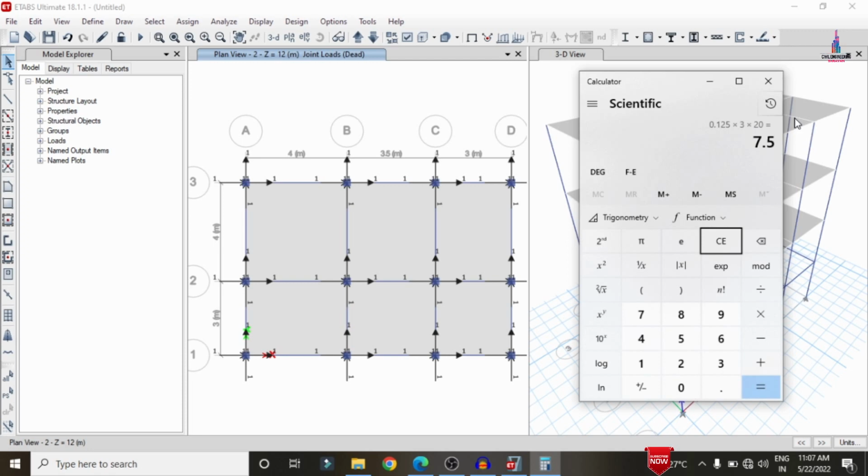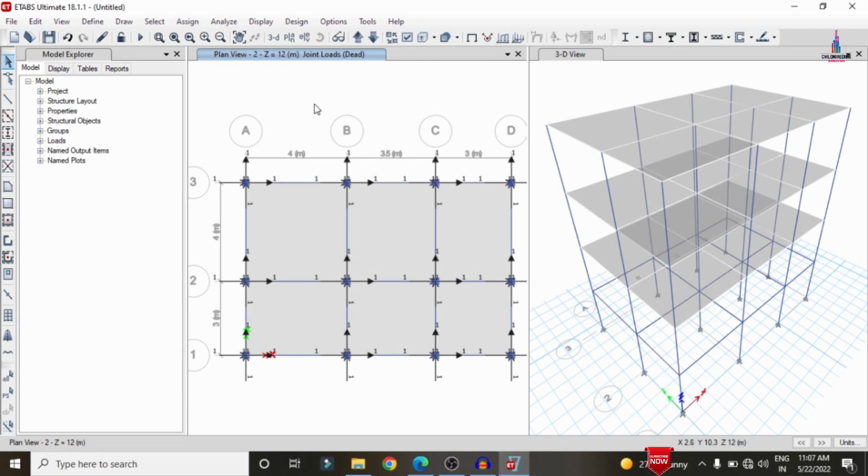So for assignment of the load for the external wall, internal wall and parapet wall loading conditions, we need to select the particular beam sections according to our consideration. Or else, if you want to design a critical structure, you need to apply all the combinations of the loads to the beams. So here I am selecting the external walls for the respective consideration.